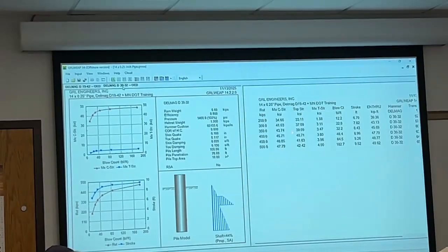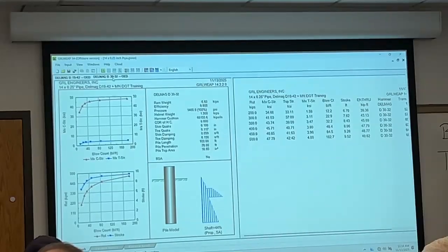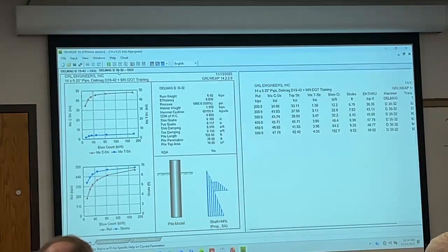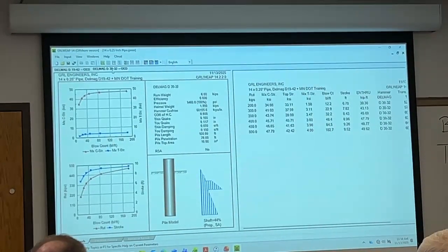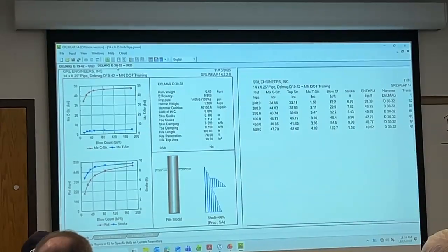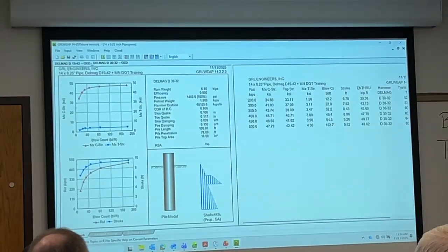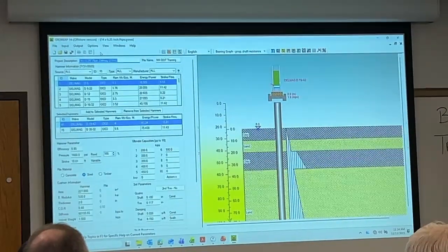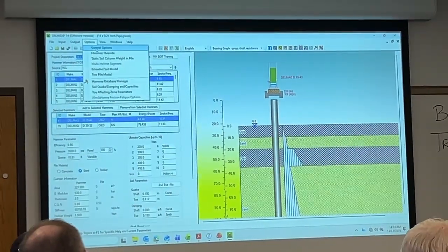So we're measuring a stress slightly in excess of that at the top, but the maximum at some other point in the pile is 45. So that's past the yield strength. So this is not good. So our D19 was too small. The D30 is too large. At least it's too large on the maximum hammer fuel setting. So let's try to cut the fuel down on this D30.